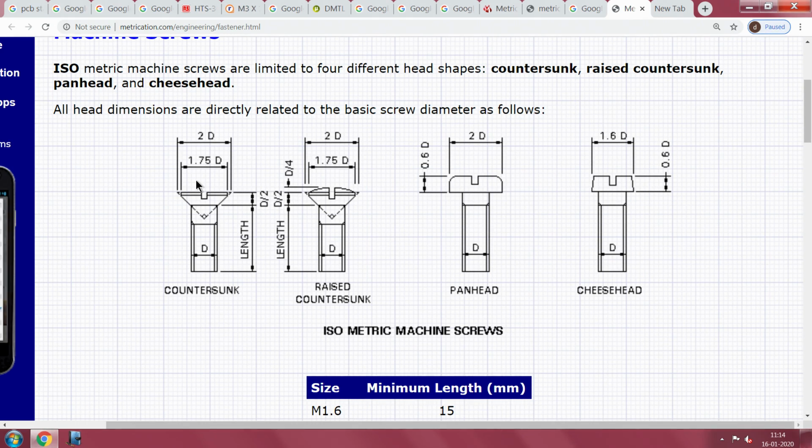Even if there is a 0.1 mm variation in 148 mm, a countersunk screw with a fixed riveted nut will not fit properly. In those cases, we cannot have riveted nuts; we require a floated nut which can take that little bit of variation, but invariably floated nuts require a very elaborate arrangement.